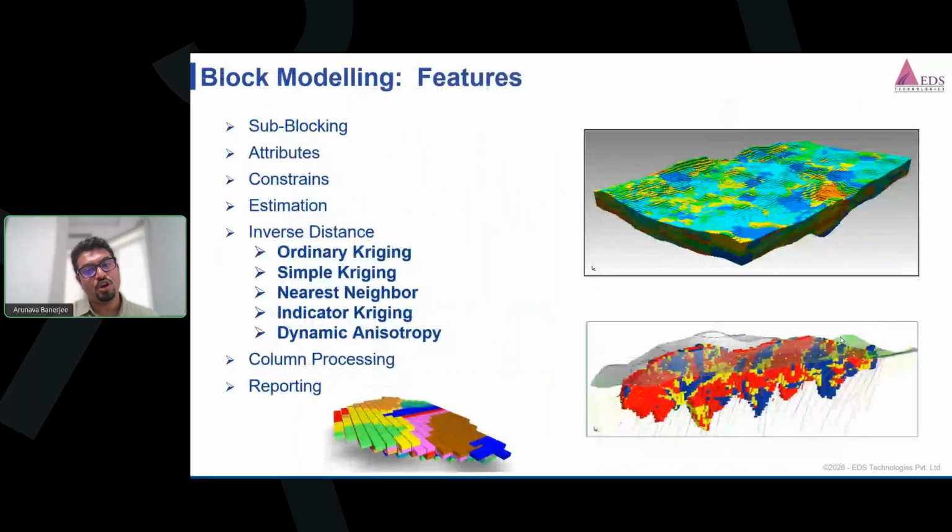So after solid model and validation, the next is the block model. We can create an entire envelope for an area within the lease boundary. And then we can create a block model .mdl file with user block size. The user block size may be 1/3 or 1/4 or 1/5 of the borehole spacing. And then the z value is similar to our bench height. But sub-blocking options are also available in Surpac software to increase the accuracy.